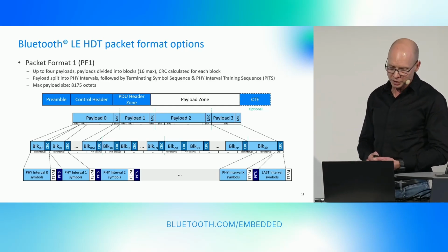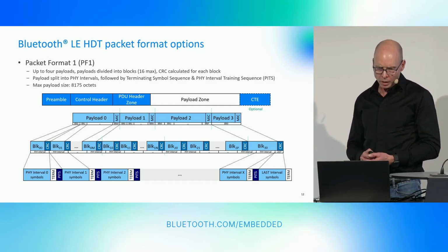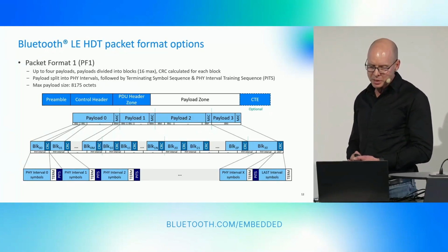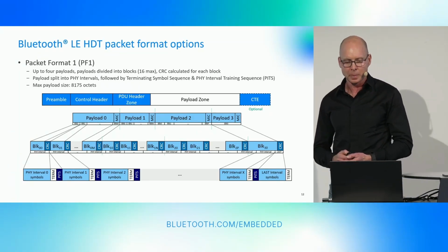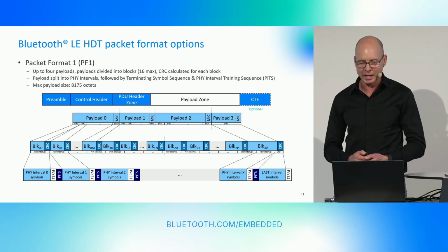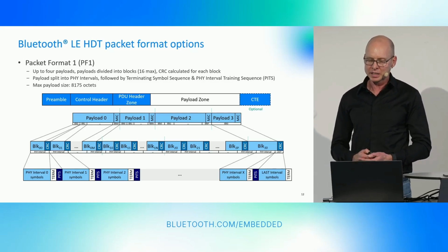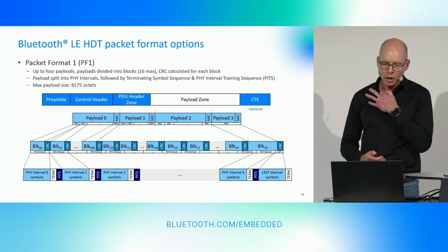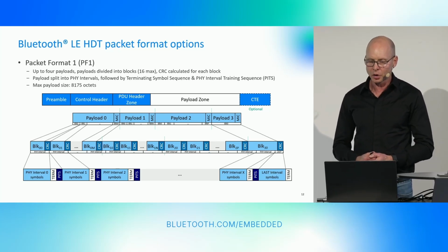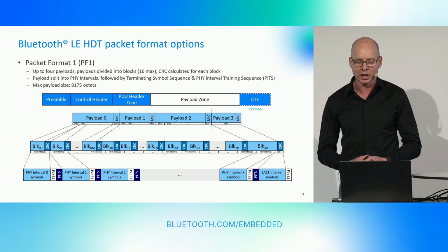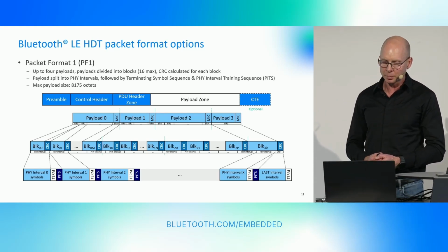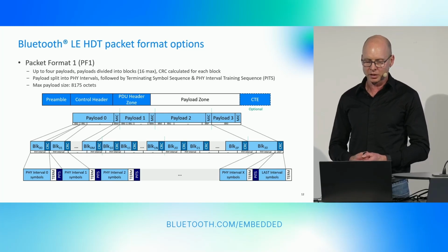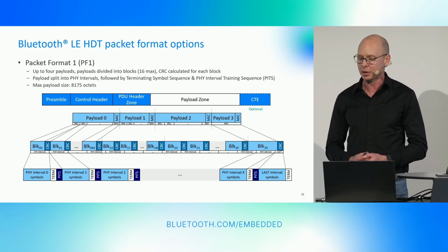And then a couple notes here. A packet can be constructed with multiple short transmission blocks, each protected by its CRC, as you can see. This is effective for mitigating the impact of interference, and it's efficient since you only need to retransmit the failed blocks. Also, you can selectively acknowledge part of a payload without having to acknowledge all of it. Each block can be acknowledged separately. This means that damage to one block doesn't necessarily mean the other transmitted blocks can't be used.